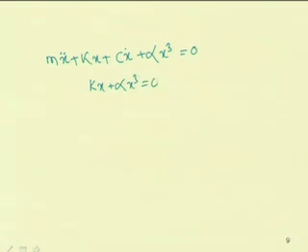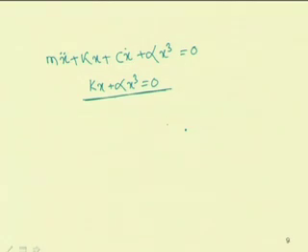In the case of a spring mass damper system with a nonlinear spring, we have written the equation in this form: m x double dot plus kx plus c x dot plus alpha x cubed equal to 0. In this case, for steady state, I can have kx plus alpha x cubed equal to 0, and by solving this equation, I can find the equilibrium position. One can make a qualitative analysis to study how the response behaves with time about the equilibrium position. That can be studied by using qualitative or quantitative analysis. Later we will study this qualitative and quantitative analysis.